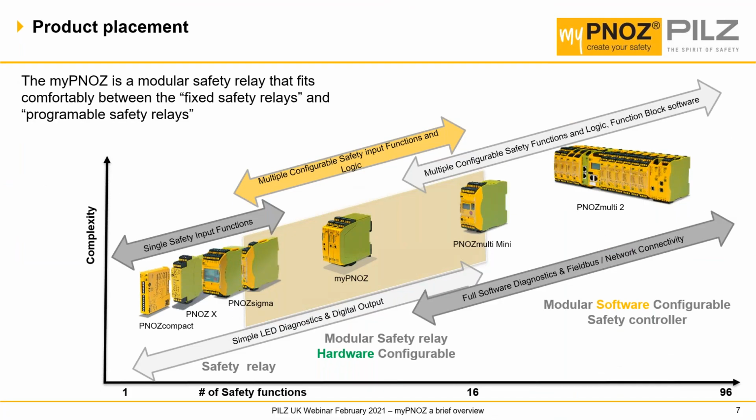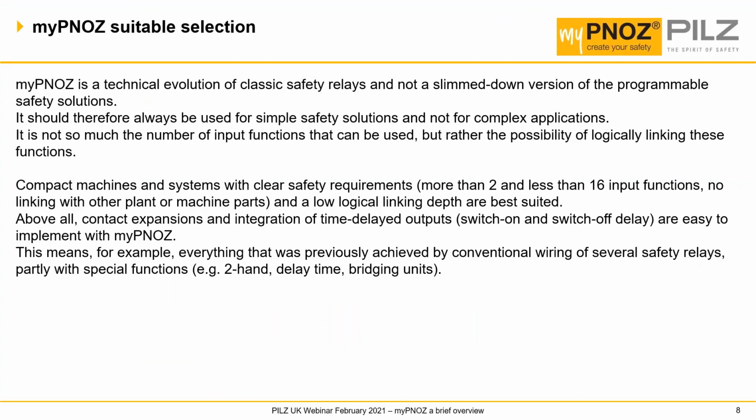So where does the product sit within the Pilz range? It's aimed mainly to sit between the standalone safety relays and the multi-programmable relays. myPNOZ is a technical evolution of classic safety relays. It is not a slimmed down version of the programmable safety solution like the PNOZ Multi.